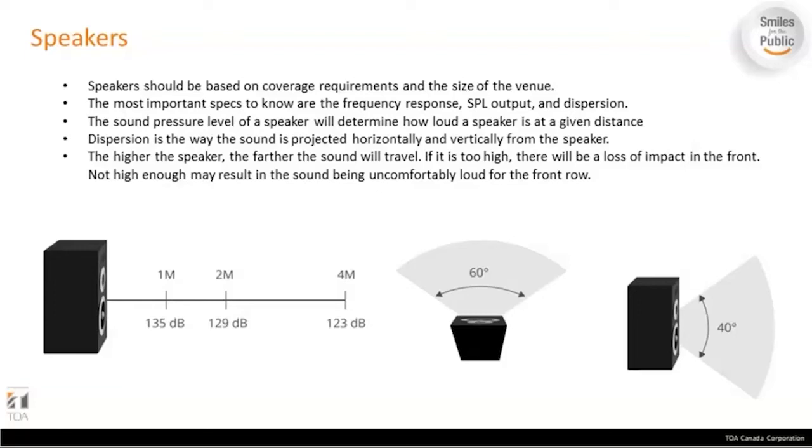So the height at which you install the speaker is also very important. We see a lot of customer calls where the recommended height after the design is 7 feet and they install it at 9.5 feet, and then they say, oh, it sounds muddy, it doesn't sound right. Because the farther it goes, you have to open up the volume even more, and it's not going to sound right. So the placement of the speaker is very important as well.